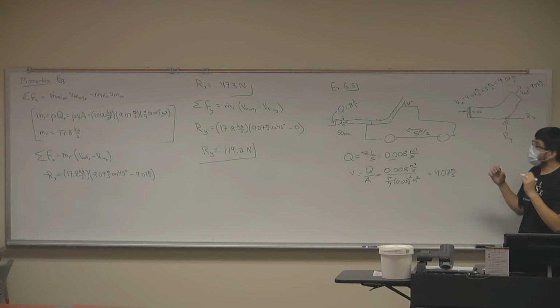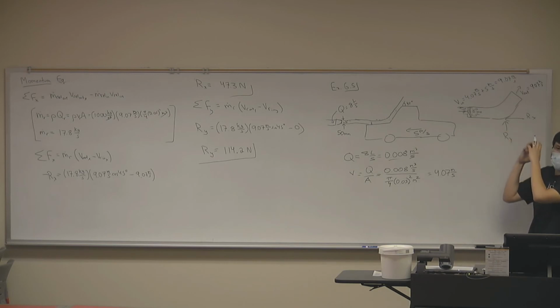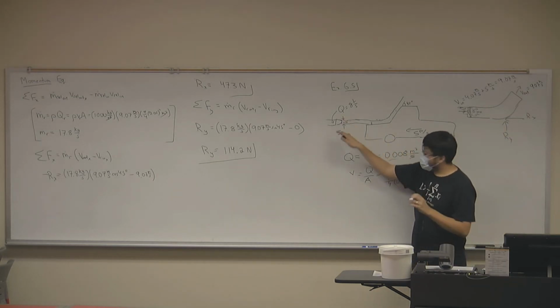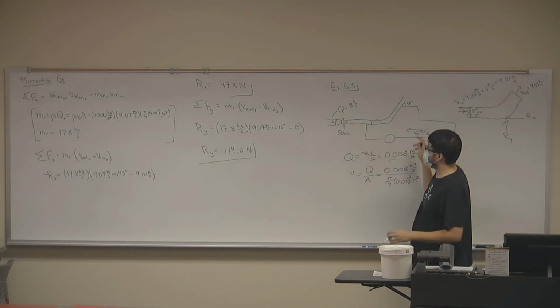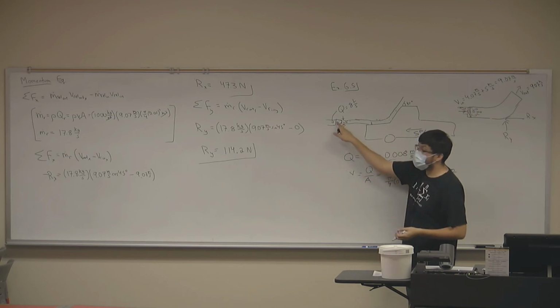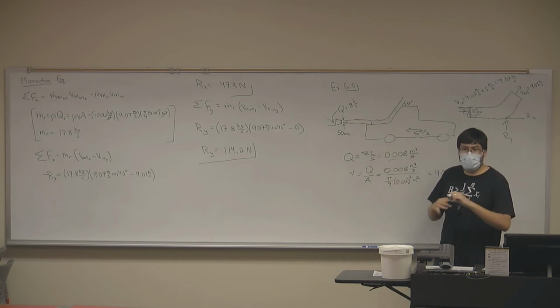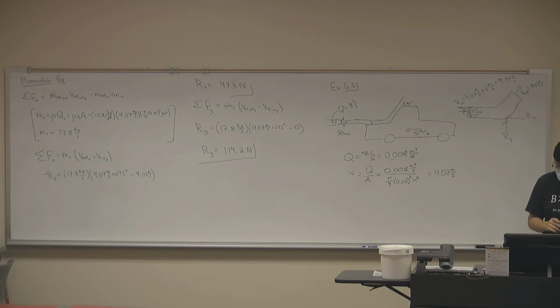So what you have is essentially a volume of fluid entering your control volume at a speed of 9.07 meters per second. So it has to be your relative flux, because even though the mass flux that leaves the hose is 0.0008 times 1,000, about 8 kilograms per second, what enters your control volume is more than that, because you're moving towards it. That's why we have to use the relative one.